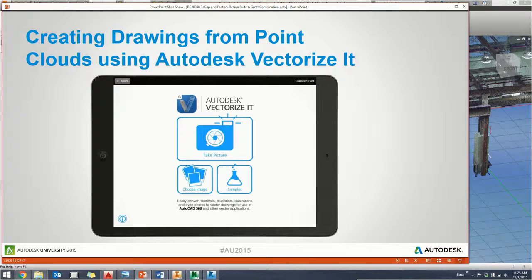But I'll be honest, I went into a job site a couple of months ago and they were generating line work from point clouds. I wanted to see how they were doing it. They were taking the point cloud in AutoCAD, getting it in orthographic view, and getting enough of the points to look like lines that they would simply print the viewport as it was.